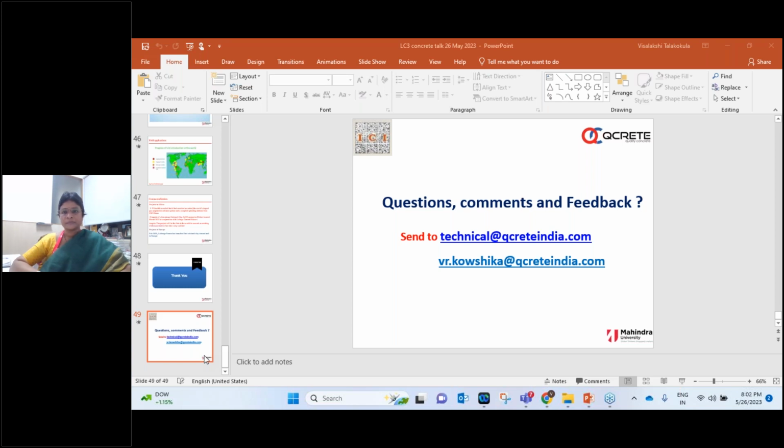Thank you, madam. Next question is, at the time water is added to concrete, how much heat is produced in LC3 cement type concrete? Yeah, I've already mentioned in that graph. If you compare the heat generated or evolved in the LC3 system, it is much less than that of an OPC system. Okay, but more than that of a blended system. So the LC3 system falls in between related to the heat evolved. OPC on the top, the blended on the bottom, and in between is the LC3 system.